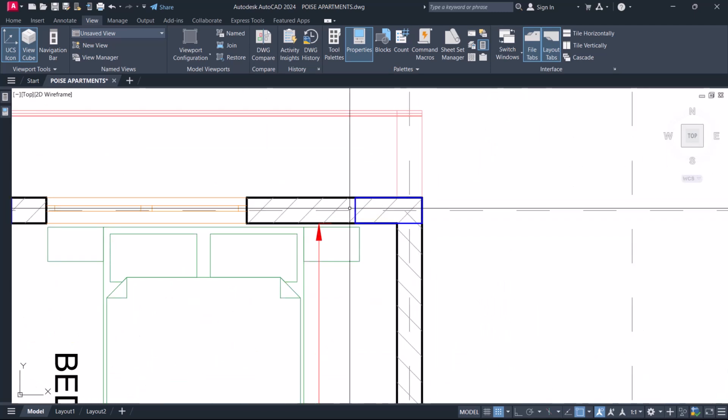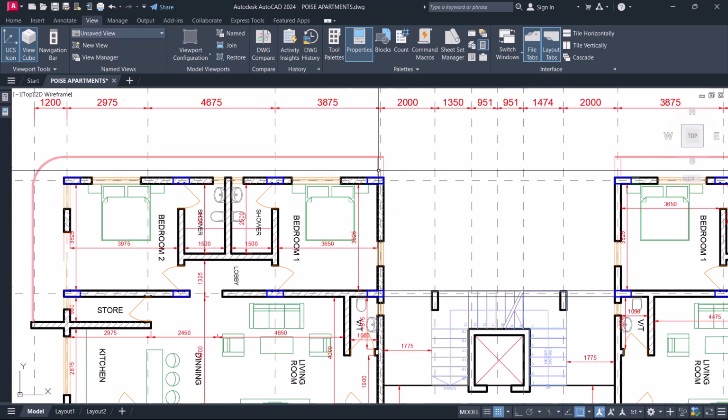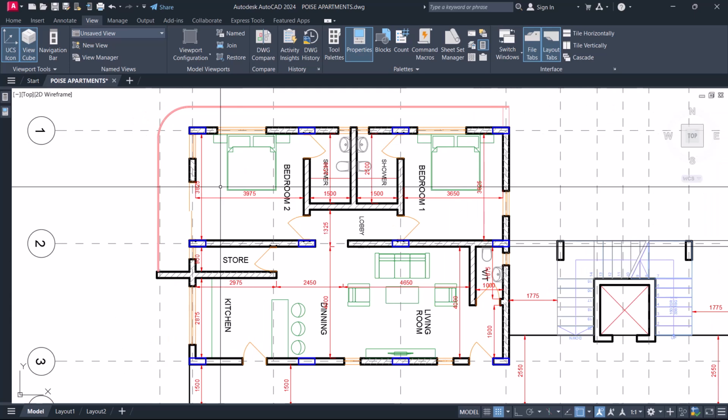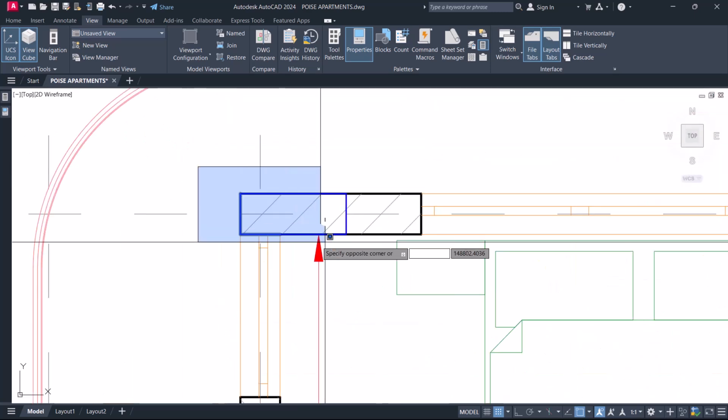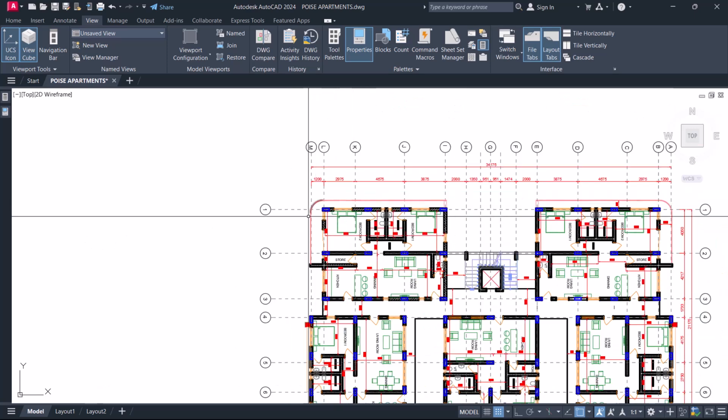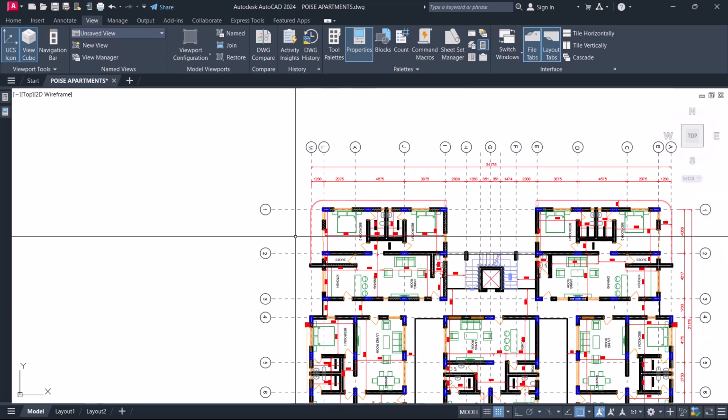It doesn't really mean that it will fail when we are designing, but it is just advantageous. So any opportunity we see when we are picking this slab layout to put our columns somewhere at the center of our slab, we will definitely take up that opportunity.